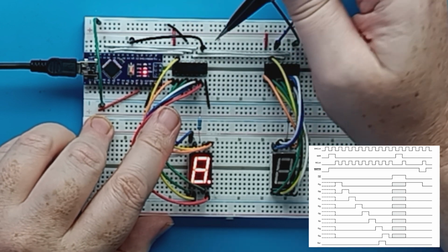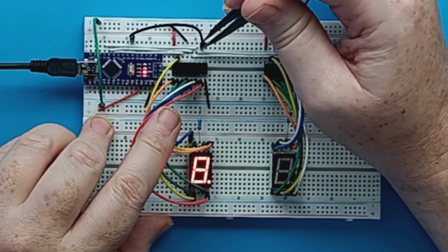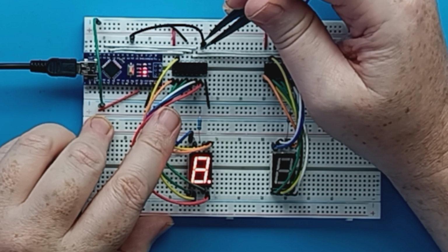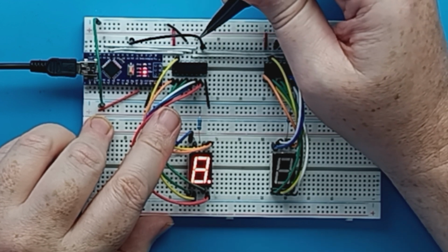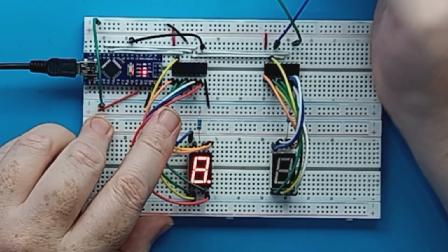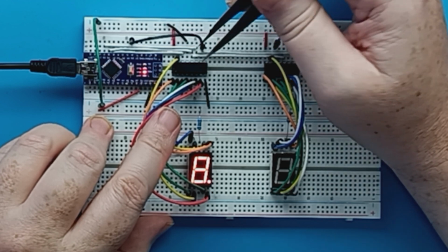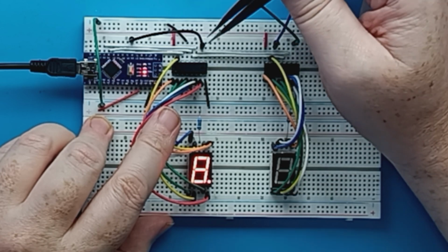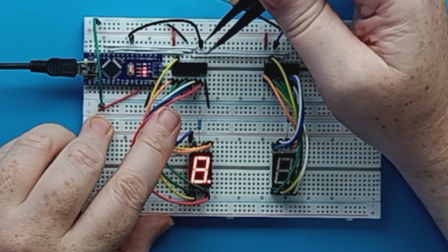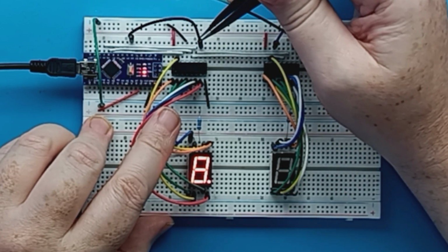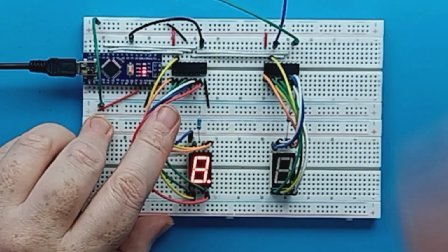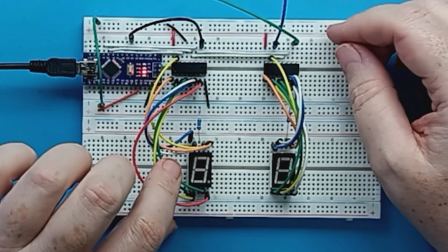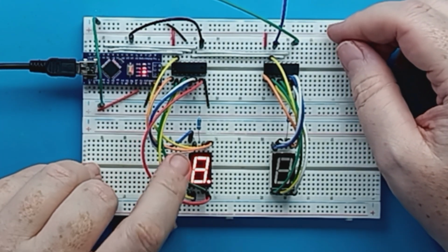To actually reset it, yes, you need to pull the line low, but then you need to pulse the R clock line as well to clear the output memory. What I was seeing before is if I wasn't invoking the R clock line after doing the clear, I was still seeing junk data on the display. So anyway, you can see at the moment it comes up clean and it displays.